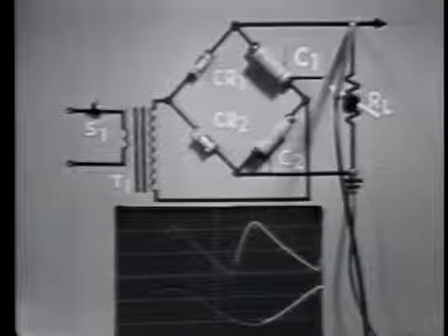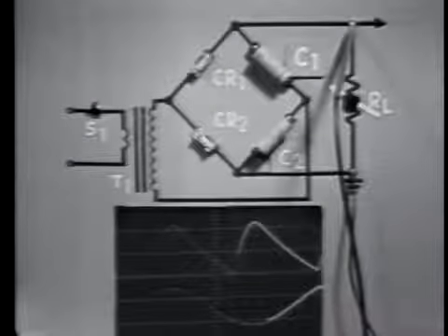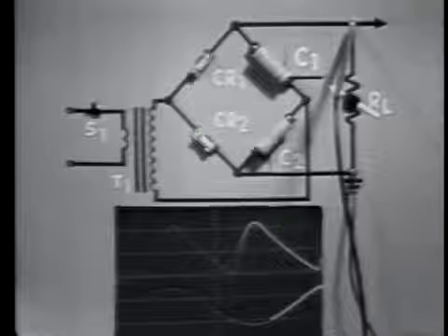Notice also that the ripple amplitude has increased. Now, these effects on a load change occur because the load change changes the discharge time of the capacitors.